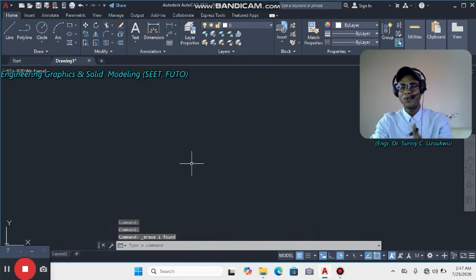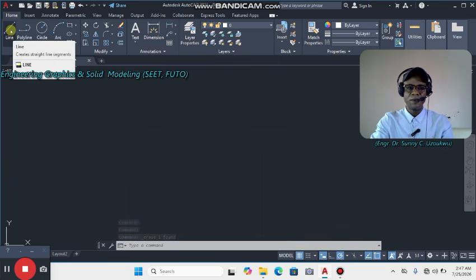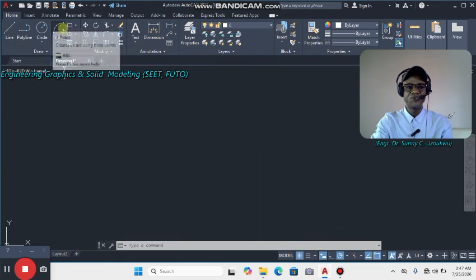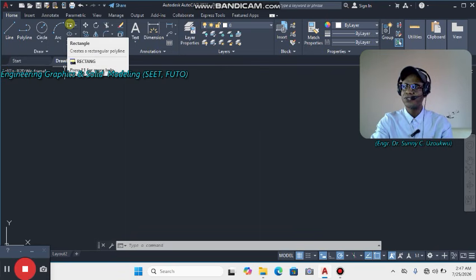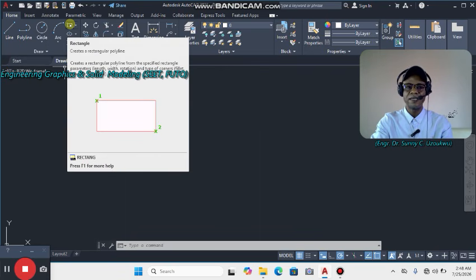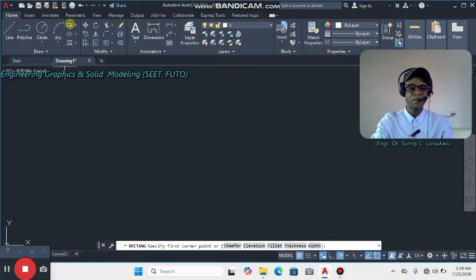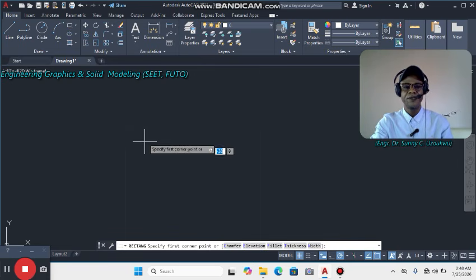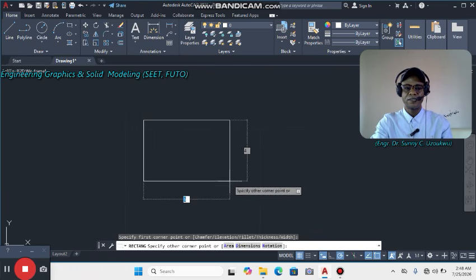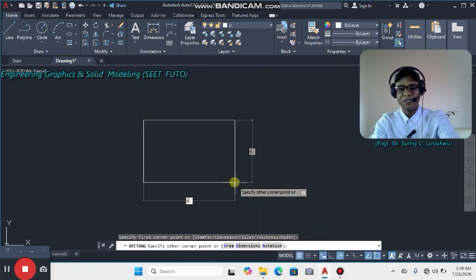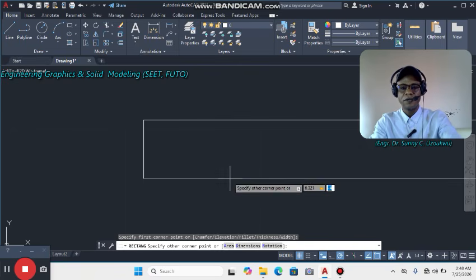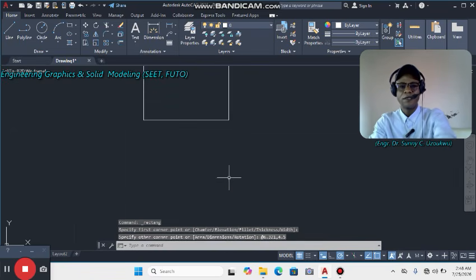Good. Someone who wants to do something faster can, instead of going through the line, go through rectangle. Shortcut REC, enter, that gives you a rectangle, or you click on the command directly and get it activated. At the end of the day, you come to the place of interest, pick it, specify the same dimension, 6.231. All right, the corresponding part, that is 4.5, and that is that.